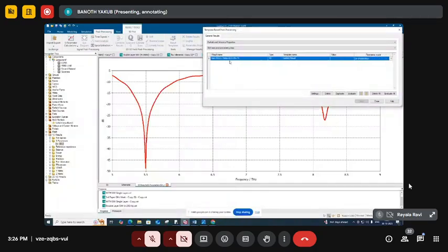So you can see here the gain IEEE, theta 90 degrees, phase angle 10 degrees, single direction far-field results. Theta is 90 degrees, and the phase you can change from 10 to 150 degrees. For that purpose, select this option, and you can also select this one.